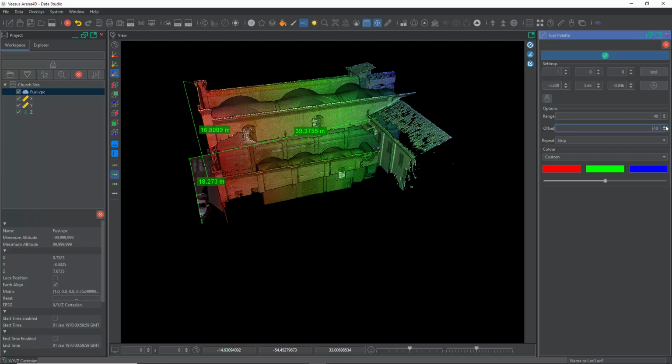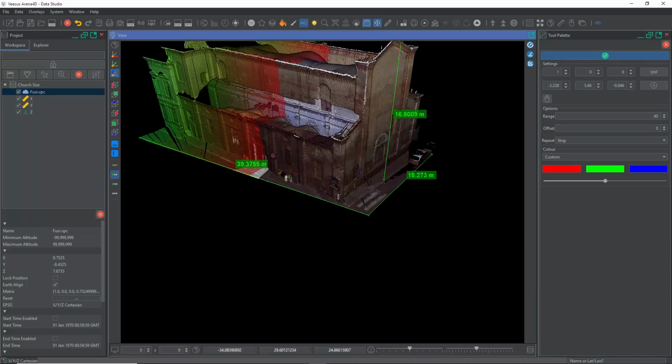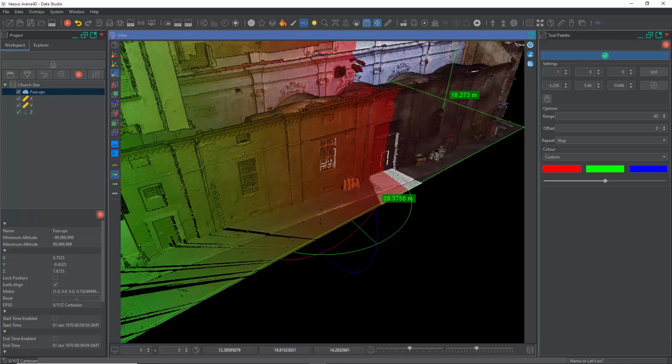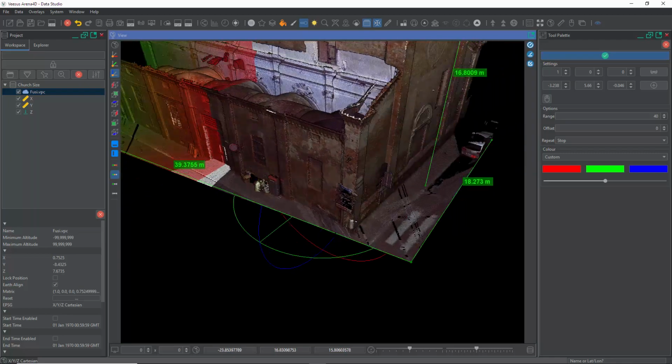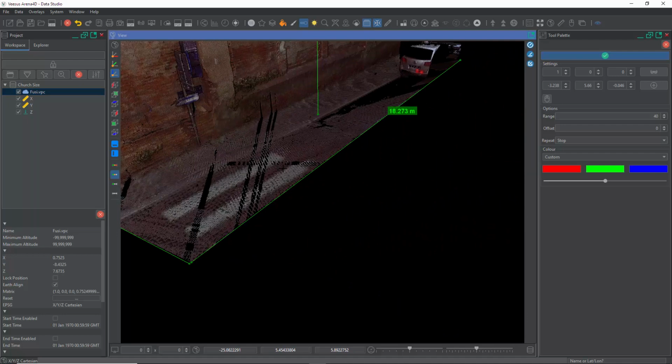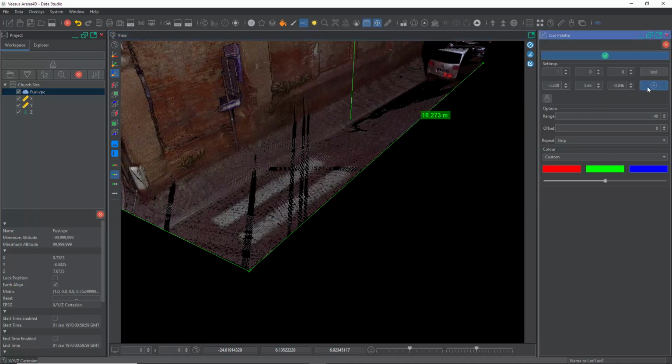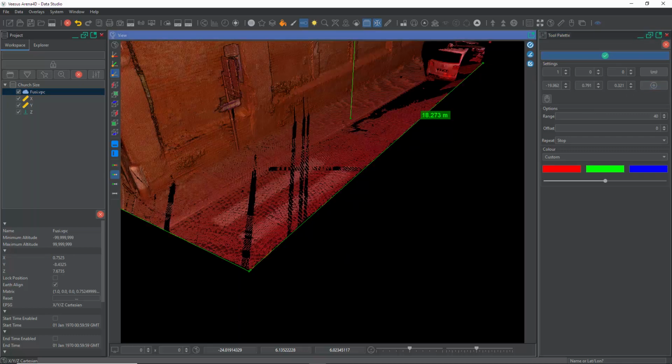But if you don't wish to play with the offset, we do have a very quick way of doing this, which is using the select plane option. Clearly we can see the starting point is incorrect. The plane is here. I wish to put it on the edge here. So what I'm going to do, select plane is blue, my crosshair is active. I'm going to click here.